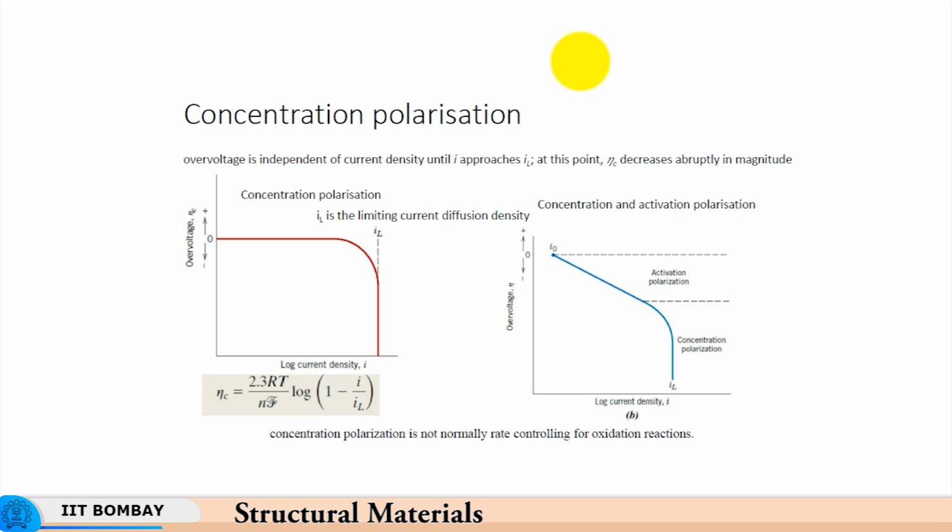On the other hand, if you want corrosion protection, then you do not want reaction of the corrosive environment with the surface, due to which you would make sure that these reactions are such that the rate of reactions is so slow that the corrosion or removal of material from the anode is minimized or completely prevented.